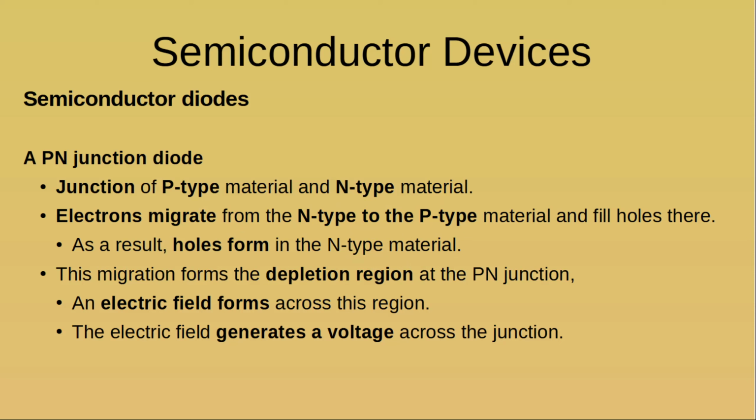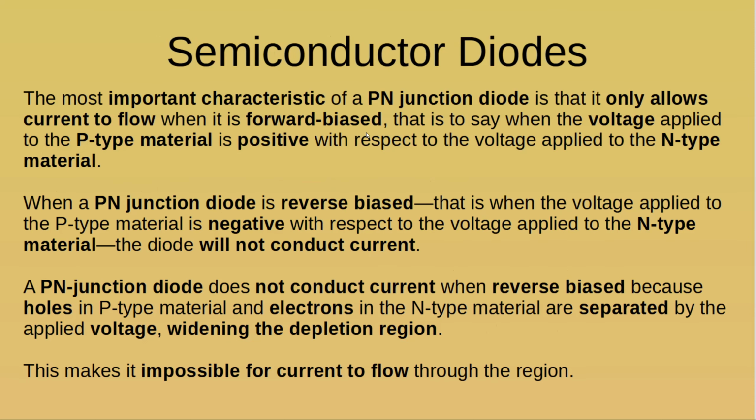As we apply an electric field or electric force across the region, you're going to supply electrons into the N material, or the P material, not N material, and supply holes in the other, and you're going to change that depletion region. And you get a voltage across it, which is part of that threshold voltage we talked about, part of the energy gap.